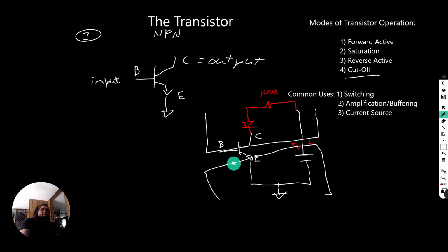It's, again, like we talked about, basically like a switch. It's just a voltage controlled switch, and we need that 0.7 volts, typically at the base, to turn the transistor on. So what we don't have here is any bias voltage, and that's why the transistor isn't conducting.